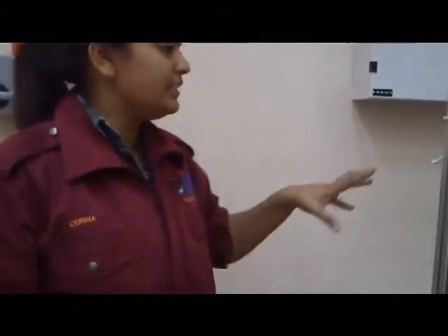So now for this week we have decided to do 3 objectives. Our first objective is to determine the decay rate of the system using different rod diameters. The second objective is to determine the natural frequency of the system for different rod diameters and compare it with the theoretical value. And the third one is to determine the relationship between the stiffness value, the natural frequency, and the decay rate. So now we'll start with the experiment for natural frequency.